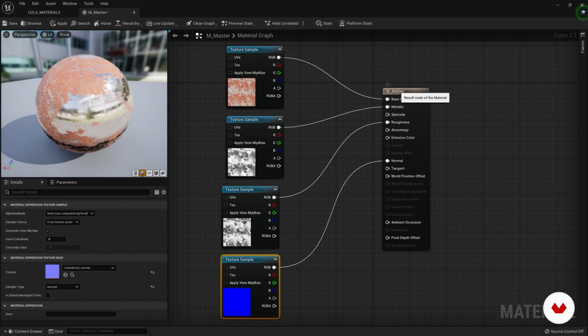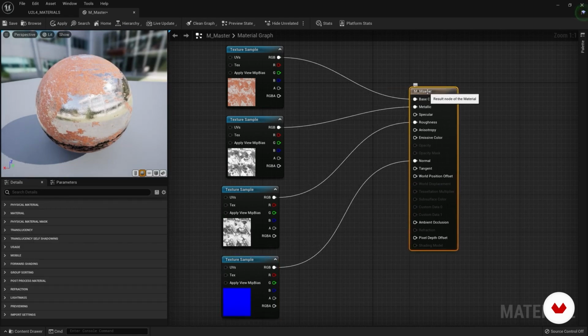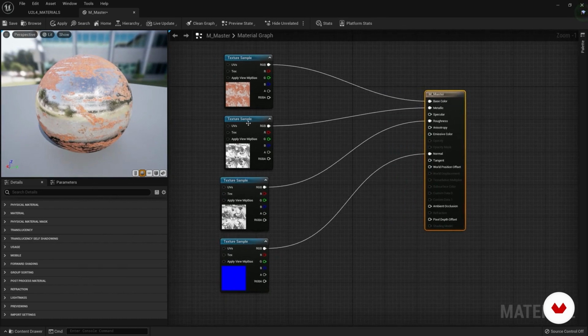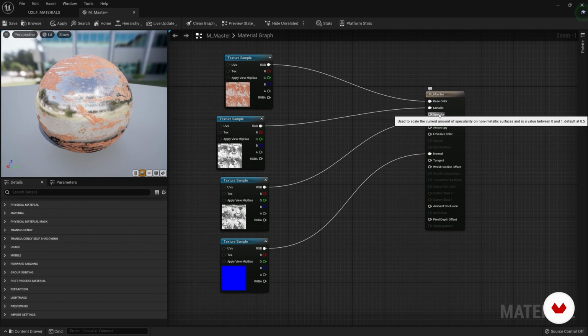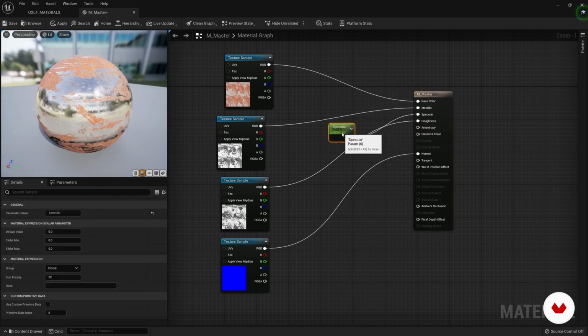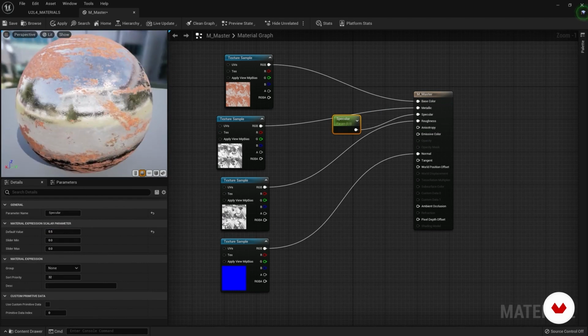Let's say we can already say that we have made the first material, but Unreal's material editor offers us tons of features. We skip the specular. The specularity factor of a material is defined with a value from 0 to 1. If we right-click and choose promote to parameter, it creates this node, where we can enter a numeric value. By default it is 1, unless we vary it, as here, with 0.5.